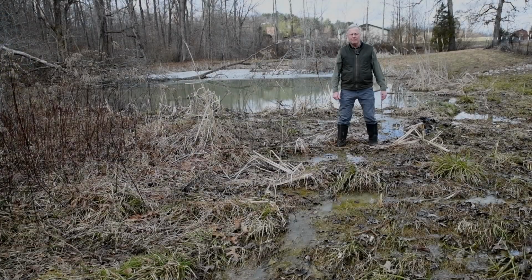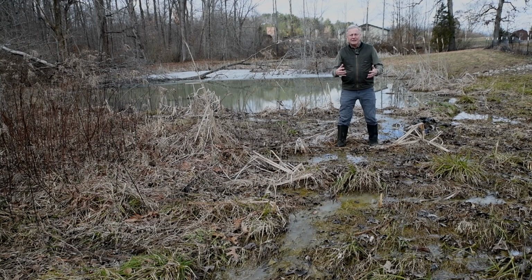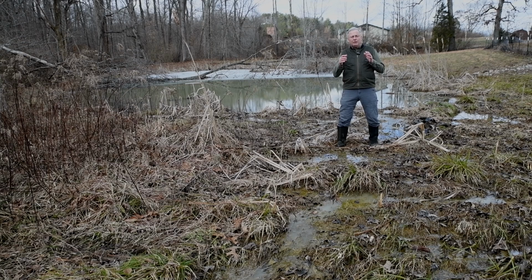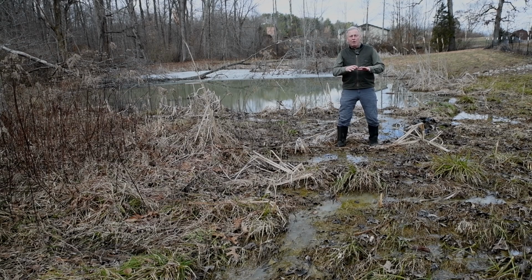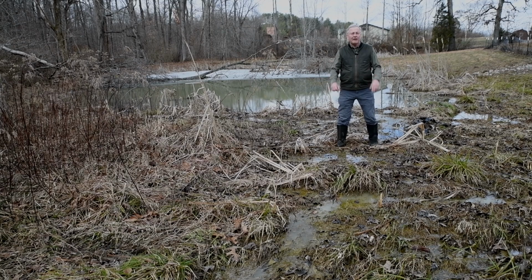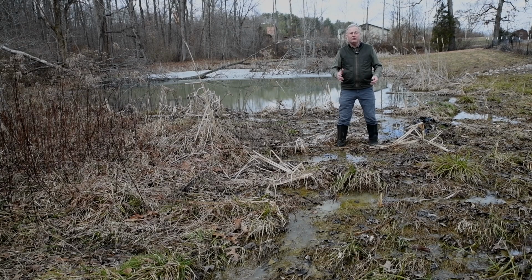I know it's important to build a wetland that holds water. What's equally important is that you build a spillway that carries overflow out of your wetland under flood conditions so there's no erosion. And what you've seen today is that you can build a spillway that carries water out of the wetland in a sheet-like pattern, and it's over a slope of less than 1%, and over time you'll have a wet meadow wetland develop in your spillway.